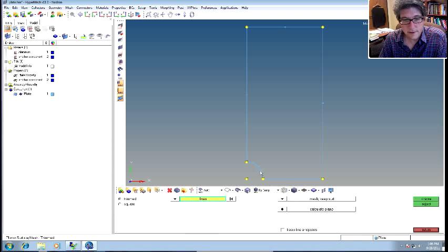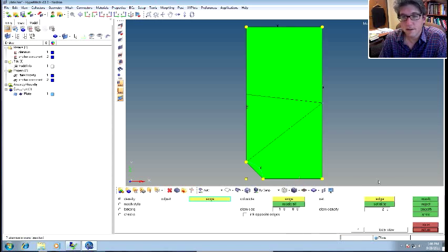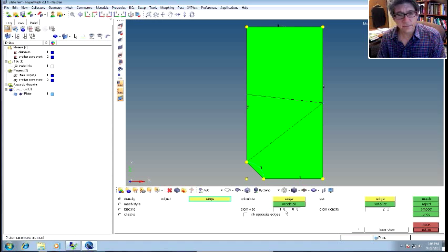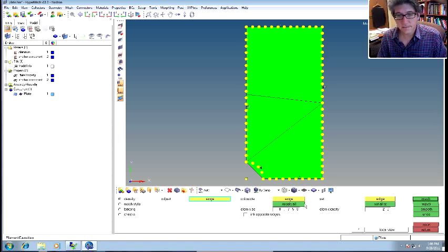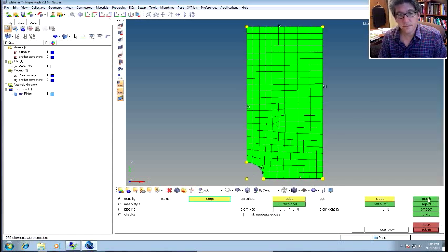Let's go back to 2D and regenerate it with planes. Let's pick the surface. The surface actually exists there, but let's do this again. You can see it did the really coarse one. Let's set the element size, instead of 1, to 0.75, and recalculate all in mesh. Even if we want to refine this here, let's make it about 0.25. We can recalculate this one to be 0.25. That's a little bit much. Let's make it 0.4.